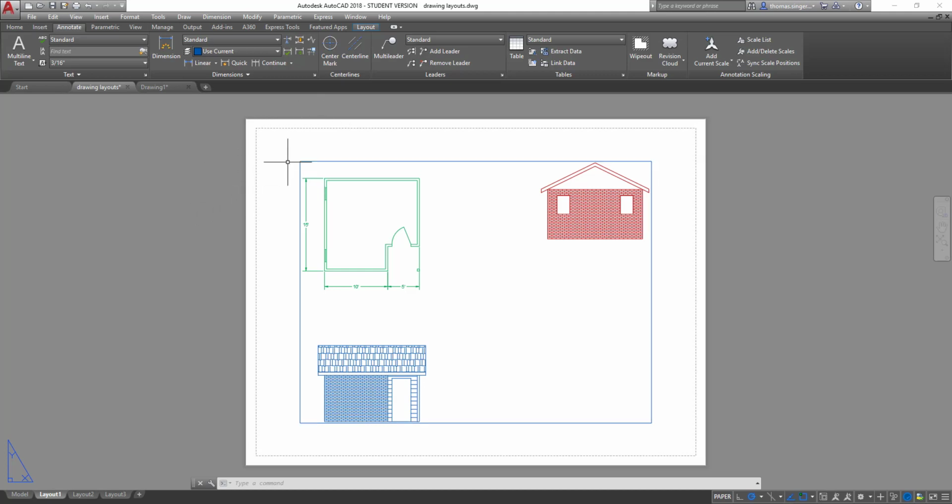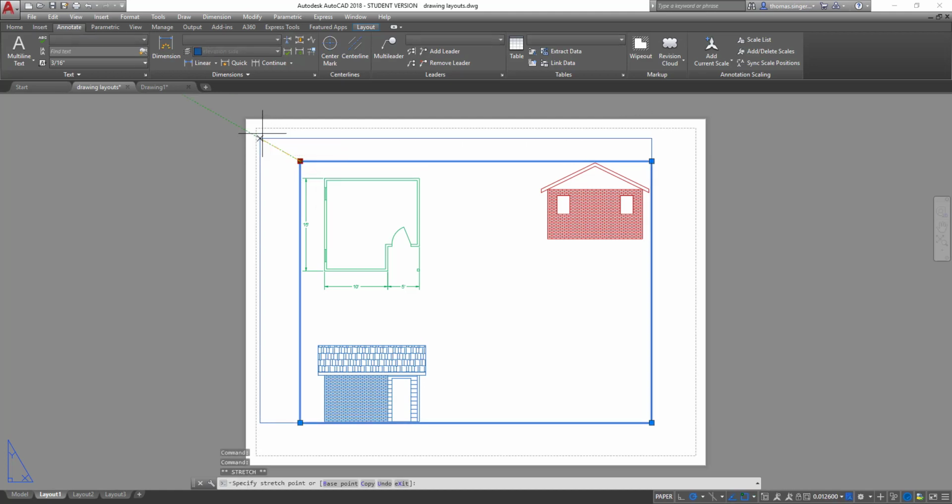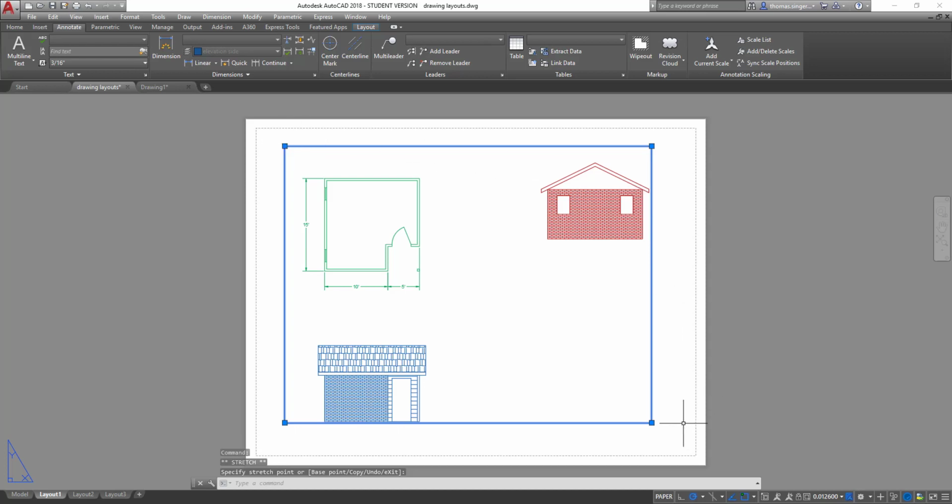The blue line, in this case blue because I've got it on a blue layer, is typically a black line, solid all the way around. That is called the viewport, and that's what we're actually able to see. This view window can be scaled or gripped or moved. It's just like any other rectangular object on your drawing, except it's on the layout sheet.